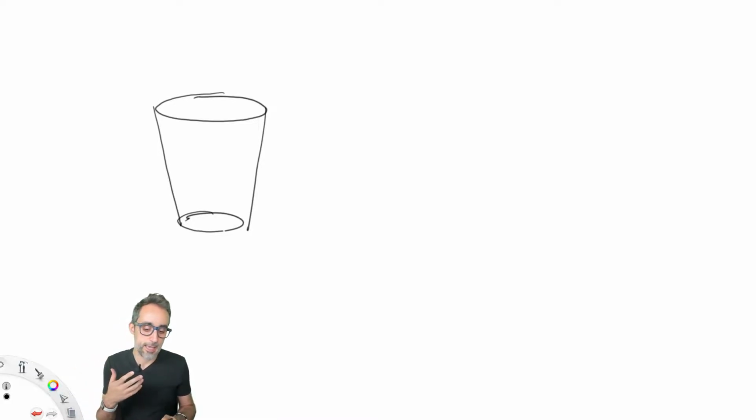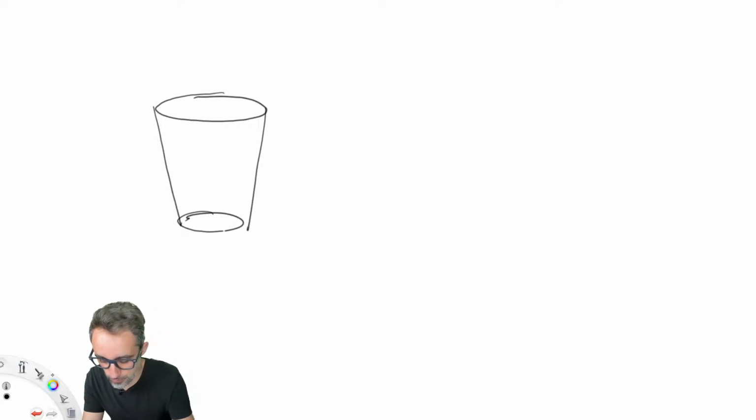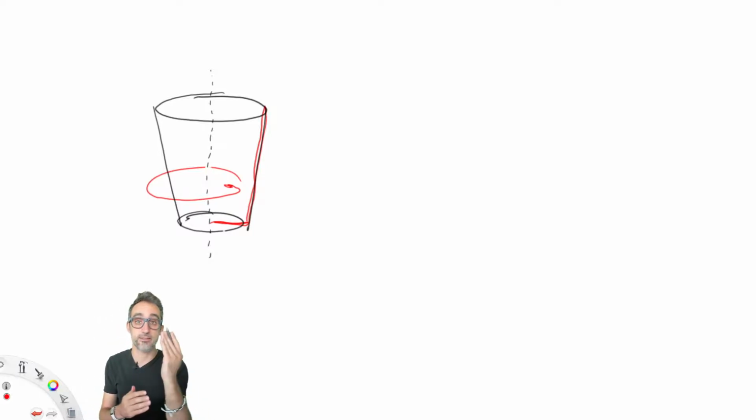All right. And if that's what I want to get to, I think that in general, a good way to get to this form will be perhaps to first model something that looks like the profile of the vase, something like this, and then by a simple process of revolution, if I revolve that shape 360 degrees, I can probably get the surface that generates that drinking glass.